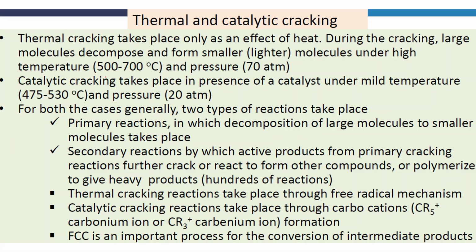In thermal cracking, the temperature range is 500 to 700 and pressure is 70 atmosphere. And catalytic cracking takes place in the presence of catalyst under mild temperature, that is 475 to 530 and pressure of 20 atmosphere. For both cases, two types of reaction take place. That is the primary reaction, in which decomposition of large molecules to smaller molecules takes place, and the secondary reaction, by which active products from primary cracking further crack or react to form other products.